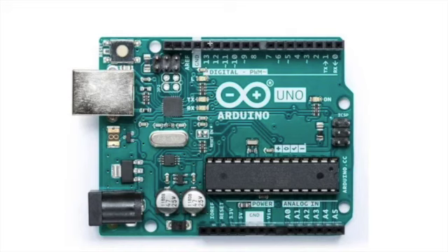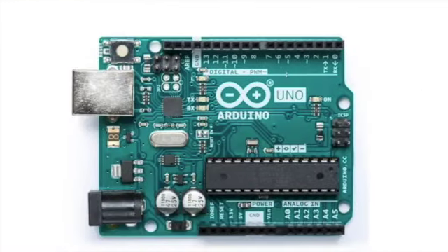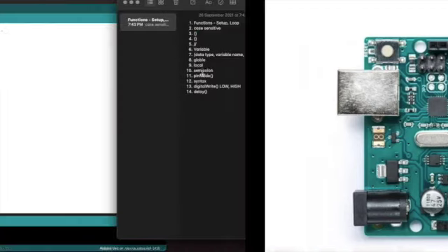In case you are giving the 13th pin as low, the digital write as low, then the 13th pin will receive 0 volts and the other pin is connected to ground, and there is no potential difference over here. Since there is no potential difference, the LED does not glow. So basically you need a potential difference to turn the LED on or off.